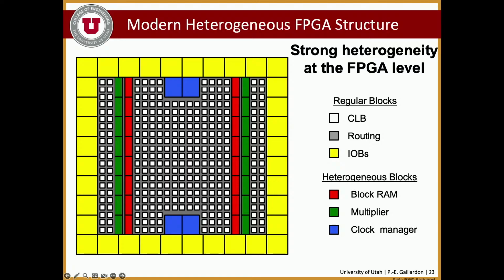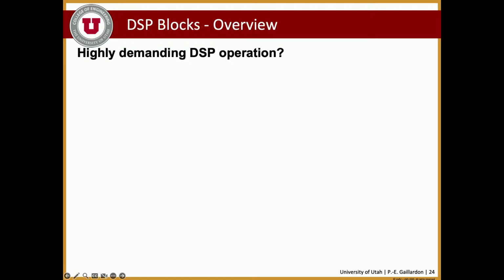are actually including heterogeneous blocks inside of the fabric. So here, memories, DSPs, and again, you're now not going to make a homogeneous island-style fabric. You're going to make that fabric heterogeneous with different types of blocks and different natures, so you can support all of that.